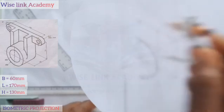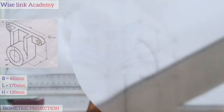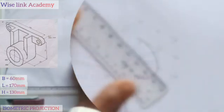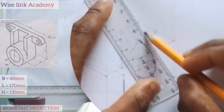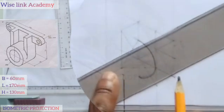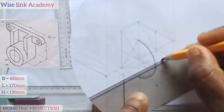Before that, I'll take my set square this way. I will draw a diagonal line at this point here, diagonal line this way, such that I will take my set square this way. At this point here, strike that same point here. Also at this point here, strike that same point on this line you have drawn.